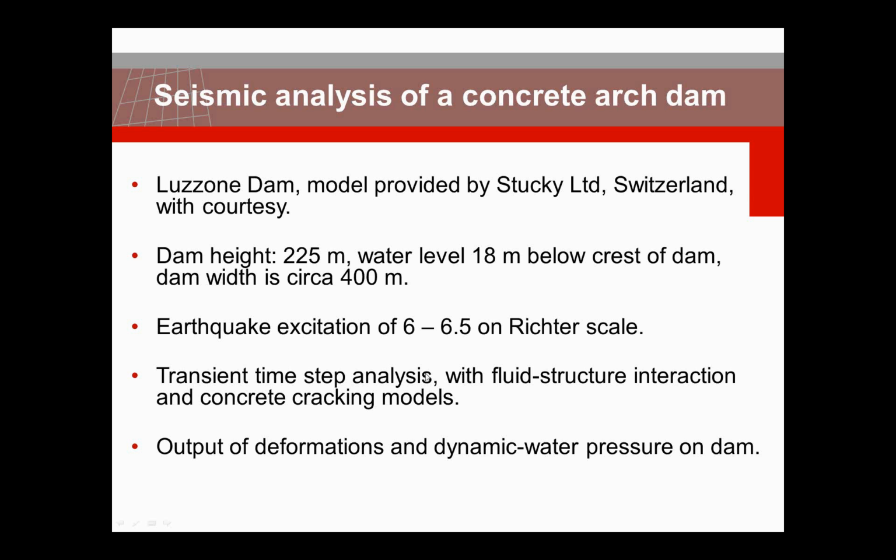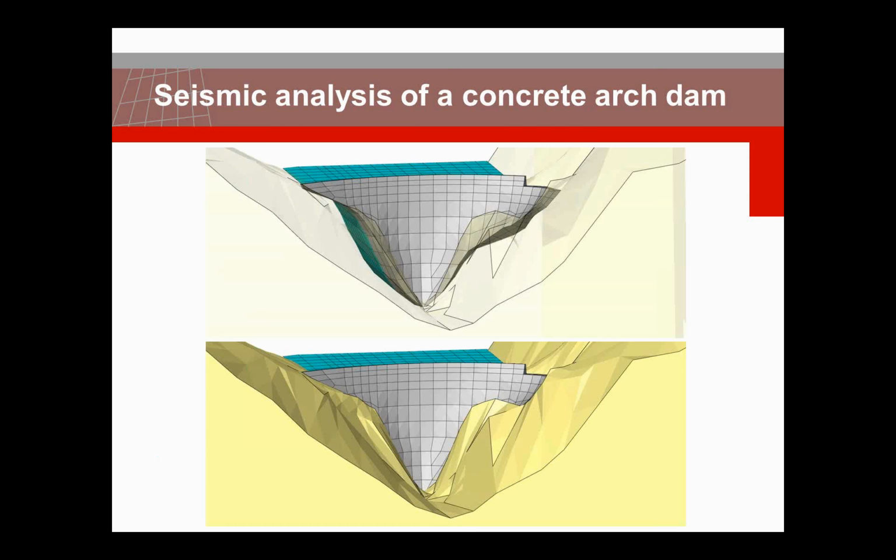And we will look not only at the dam itself, but also at the effect of the fluid on the structure, where to the concrete dam we will define a concrete cracking material model so that we can study the effect of the failure of concrete under such earthquake loading. Another aspect is that in this case study we will show the effect and the development of dynamic pressures on the dam.